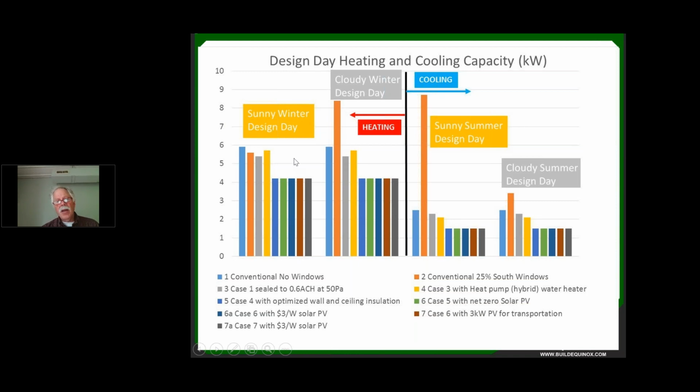But in Vermont, and as I mentioned, our Vermont study looking at 13 identical homes, they all have heat pump water heaters, they all have served fresh air ventilation, they all have high performance, low temperature mini split heat pumps. These homes work in the harshest winter climates you find throughout the US and into much of Canada. There's no ifs, ands, buts about the performance. You can read about energy, you can read about comfort and indoor air quality. These homes absolutely work, and this heat pump water heater is a big part of that overall performance. So don't let anybody tell you differently.